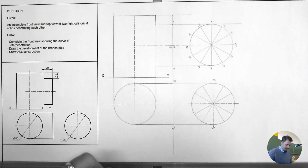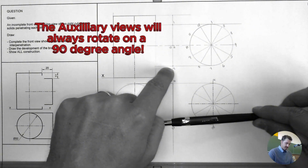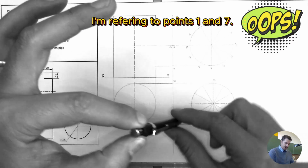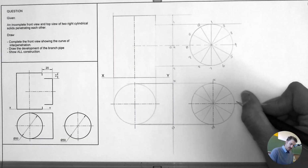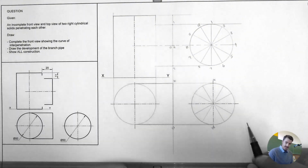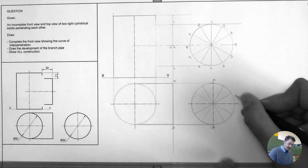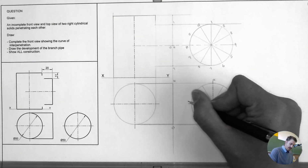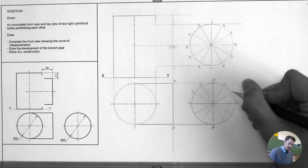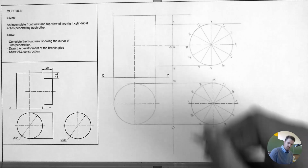So the rule applies again. If you put this down, the view that's going to be in the front, which in this case is going to be 10. If you lift it up, 4 is then at the back, right? So 10 and 4 is already placed. I'm referring to 1 and 7 now, these two. They are supposed to now be at the top and bottom. So 7 is at the bottom, which I'm going to put here, and 1 is going to be at the top. So 1, 2, 3, 4, 5, 6, 7, 8, 9, 11, 12.